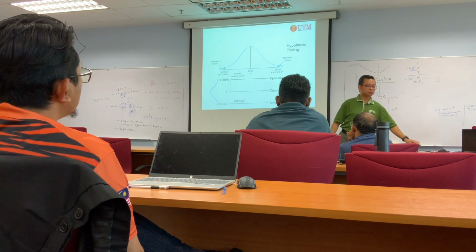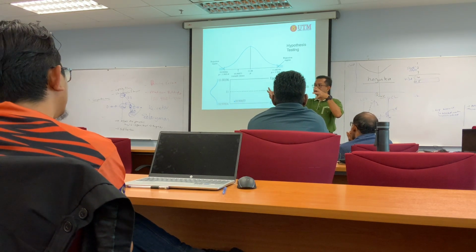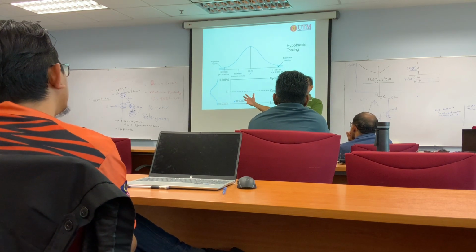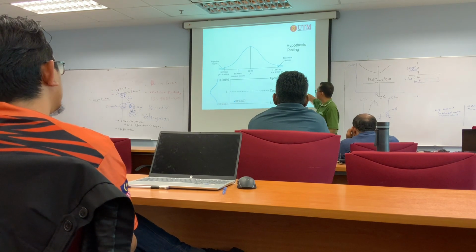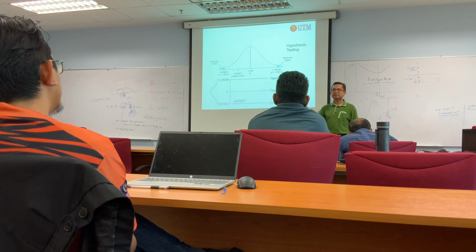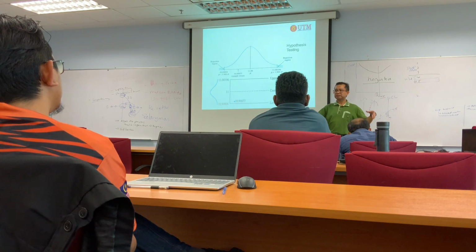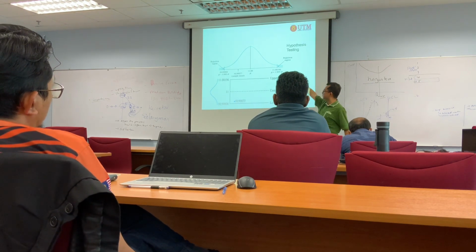We cannot simply put the sigma based on the data that we have. Maybe that is not really accurate. Or if your tooling or your machine is new at that time, you can have a very small standard deviation and you multiply by 3. So that's 3 sigma, but that will give you disaster later on. So you have to be realistic. In the automotive society, they have their ACE, so they know already what the sigma is for that particular process. So from there, they just multiply by 3, so they have the limit.